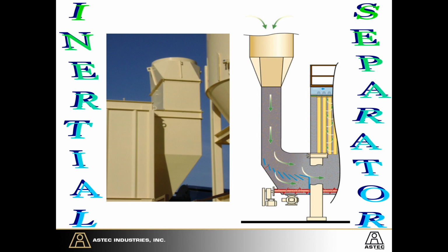The new design, or what we're mostly seeing now on plants, is called an inertial separator. It's more of an elaborate word for an elbow. As you pull exhaust from the drum, as it moves down this high velocity air, the heavy materials hit these louvers and they fall straight down into the auger. And then you're conveying most of your minus 100s straight back over to the drum. Then the lighter dust, the minus 200, gets conveyed over into the baghouse. And we've got some illustrations we'll show you a much better representation of what we got here.